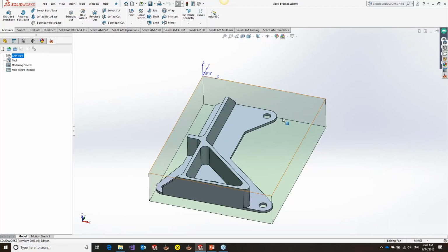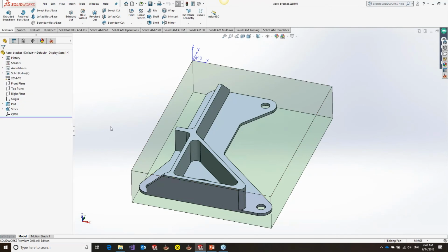and open up SolidWorks. Okay, so what do we have here? I have a part. I have my stock modeled as a separate body. I also have a SolidWorks coordinate system. These are things that you can and cannot do, depending upon how you like the demo. An important thing to note before we go into creating toolpath is I have a SolidWorks material defined on this part. So I have aluminum 2014 T6 defined on this part.